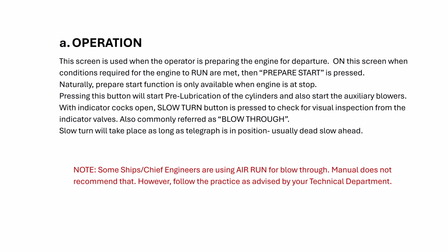Of course, the engine-driven hydraulic pump must be running. Indicator cock must be open. Or the prepare start condition must be met. Turning gear disengaged, automatic starting air start valve in auto position. All those things must be there.